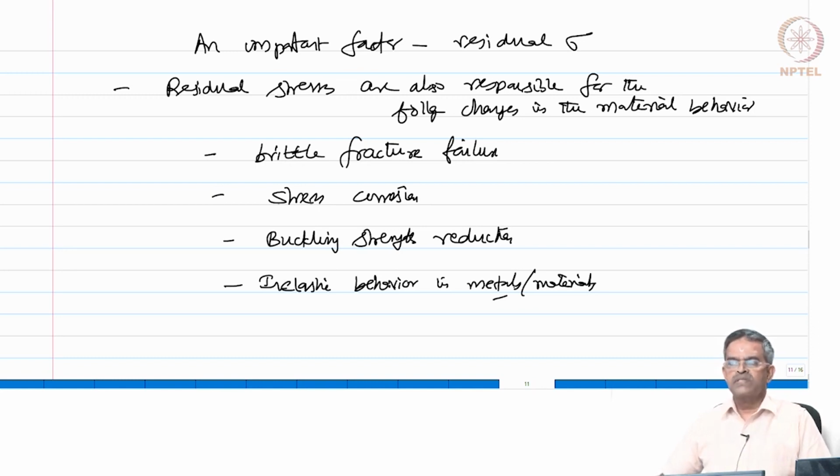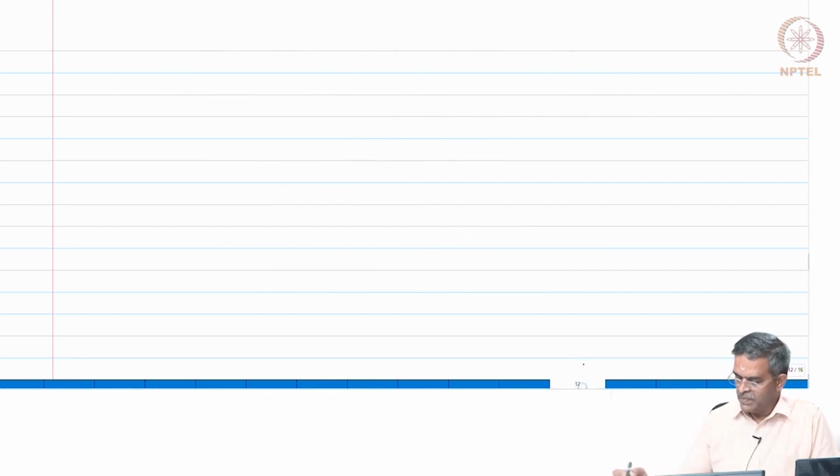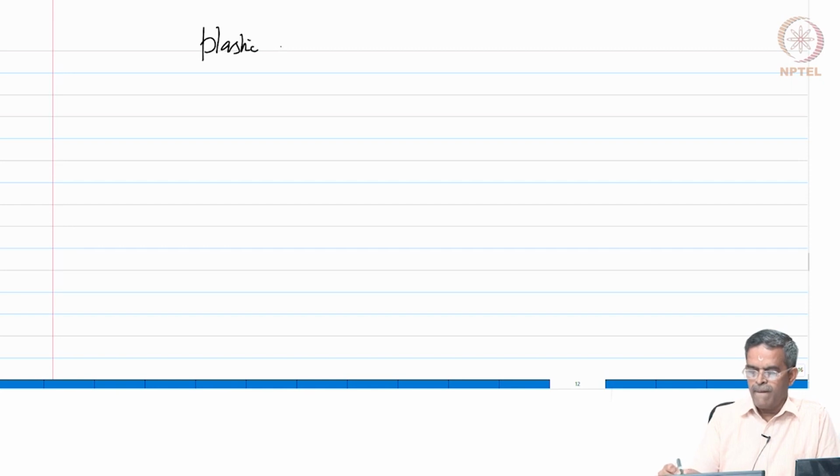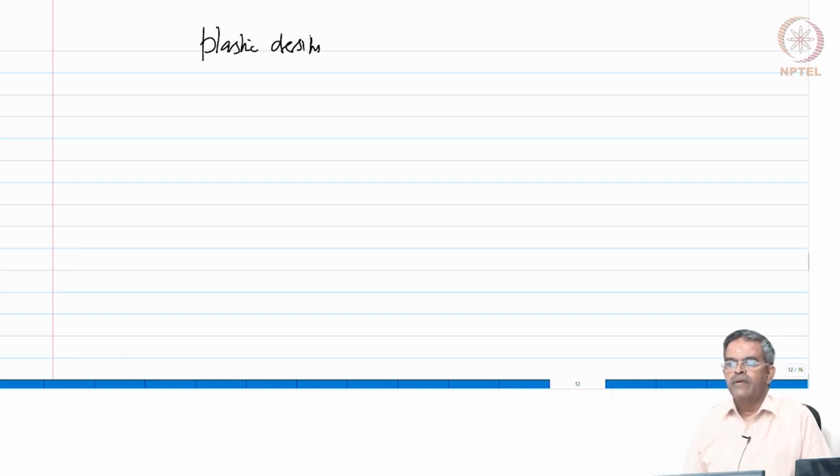The most advantageous factor of steel, as we all know, is ductility, which is a sign to use the reserve strength more conveniently and confidently. So, the ductility of the material enables a thorough redistribution of moments from the higher stress region to the next higher stress region. Thus, the load carrying capacity of the member keeps on increasing beyond the yield stress, which is enabled in other methods of design like plastic design, which is completely different and deviated from elastic design. Therefore, friends, plastic design is an effective design procedure.